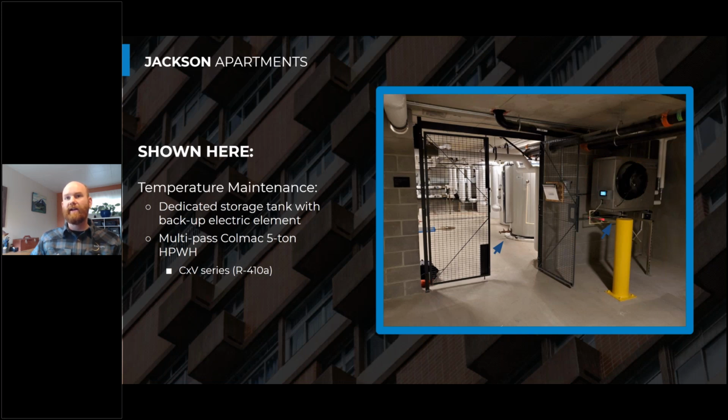It's also located outside this room because there was a product update when we were working on this. This was originally in that room and ducted out, but because the update put this fan on a hinged access door, we would have to disconnect that fan and the ducting from it every time we needed to open this panel to get maintenance access. So we simply put this one outside the room to prevent the requirement of ducting it if it was inside the room.